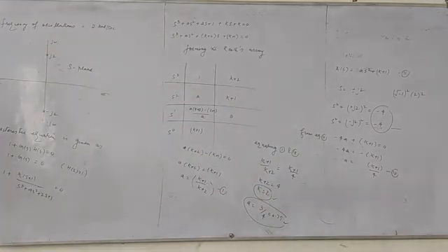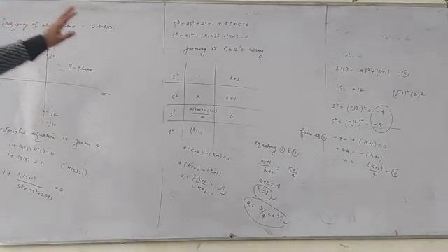Then take that option. See, very well framed question this was. What has he given, I will again repeat it. The examiner has given what? He has given a negative feedback control system where you should know the characteristic equation. How is that? 1 plus G(s)H(s) is equal to 0. H(s) is 1, so 1 plus G(s) we have to get. You have got it, you have formed the routh array.